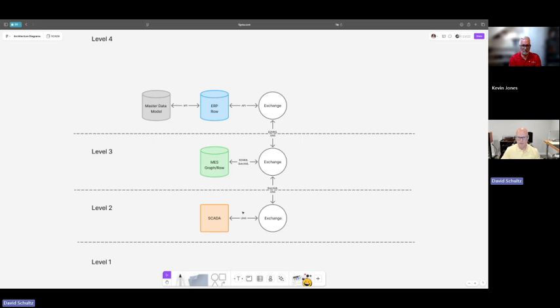The reason why we want to start doing those types of things is so now we can implement a unified namespace. The idea is we now have commonized and standardized how that information from an equipment perspective looks, even though BatchML handles those common specifications, it's not as defined within this UNS space. There was a post here recently where I commented the best part of the UNS is that there's not a standard. The worst part of the UNS is there's not a standard.